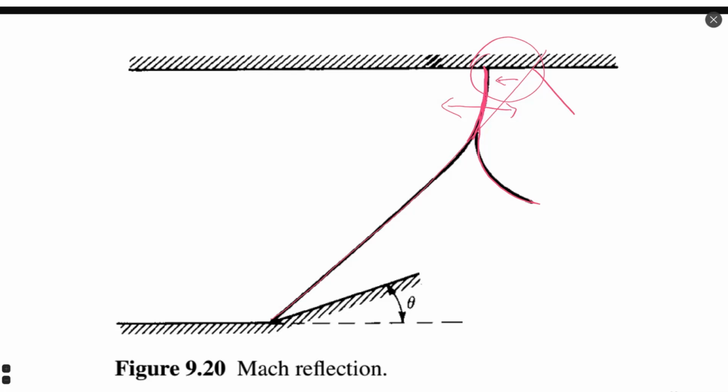And the transitional normal shock wave, because it's perpendicular to the flow, we can calculate using normal shock wave theory. We can consider this a normal shock wave, and all flow properties in zone 3 can be calculated just using normal shock wave theory, but not oblique shock wave theory. This can serve just as a reference, not as a definitive final result of calculation, because as I told you, this shock wave does not have a linear or completely normal structure to the flow.